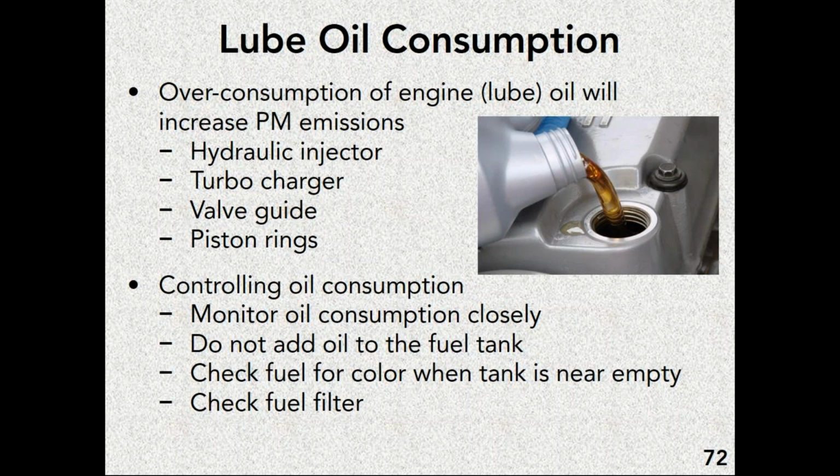In order for a piston to go up and down, the cylinder that it's in has to be lubricated properly. And because of the way they're built and because of the way they function, there's always a microfilm of oil that gets combusted every single time an engine is turned on. It's just a matter of how much. The more an engine is worn, the more engine oil it's going to actually burn. So all engines burn oil.